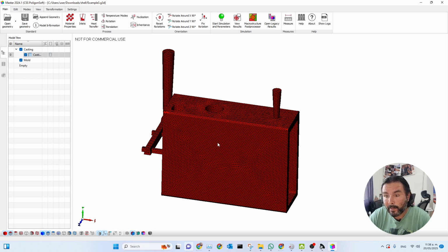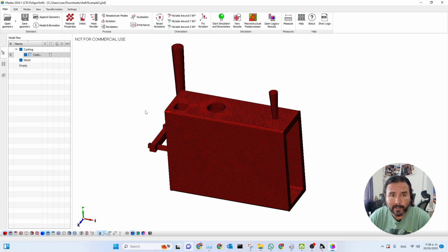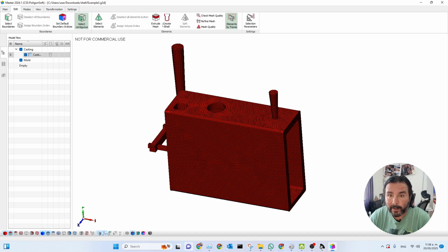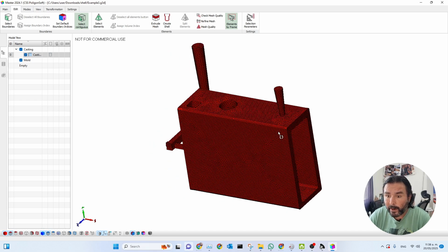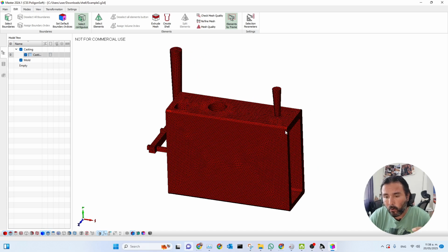We could have drawn a mold in a CAD system that repeated the external walls to simulate as if it were the sand mold, but smaller. But we can also use a tool we have in the program in the Edit tab, which is the Create Shells tool. Normally, the tool is used to create shells for investment casting, but it can also be used to create an area of sand around our part, which is the most important area for heat exchange.